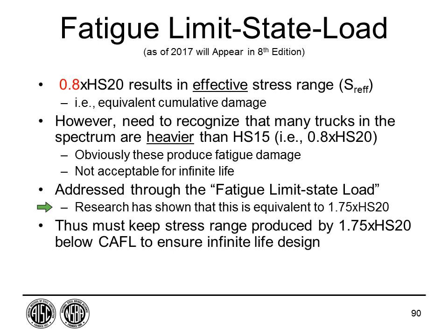Why do we care? Well, remember, we have this concept of finite life and infinite life. And to ensure I have infinite life, I have to make sure that the stress ranges that the trucks produce stay below the constant amplitude fatigue limit. Remember that horizontal portion of the line. If I assumed that this was my truck for fatigue design for infinite life, I would be wrong for infinite life only.